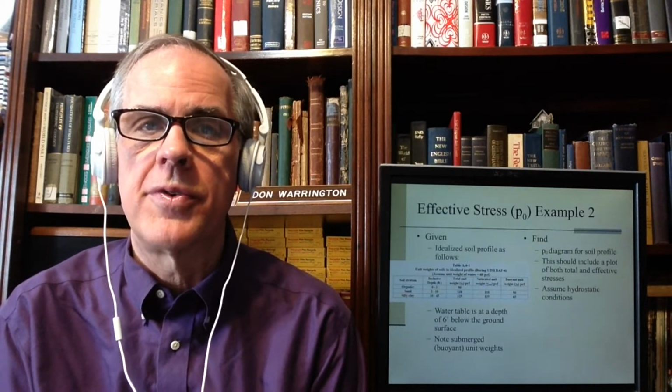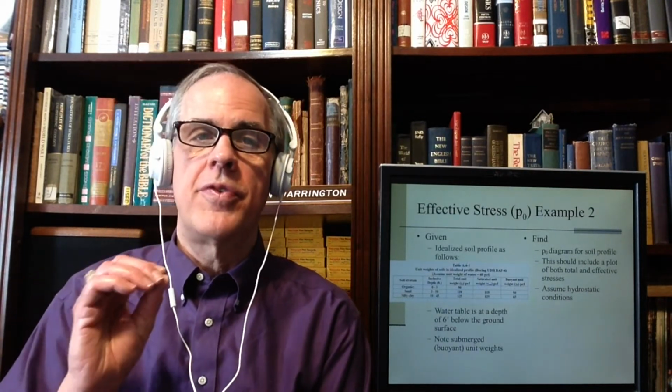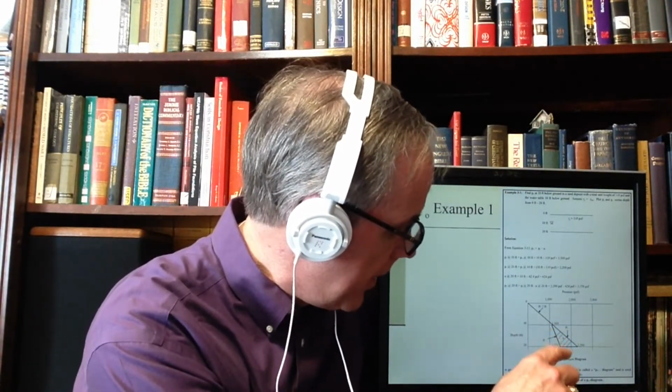Your pore water pressure, we assume for this part that it's all hydrostatic, which is Z times gamma w, the distance from the water table down to wherever you're at. For example, in this problem, the surface of the water is at 10 feet, and therefore Z is 10 feet down to 20.